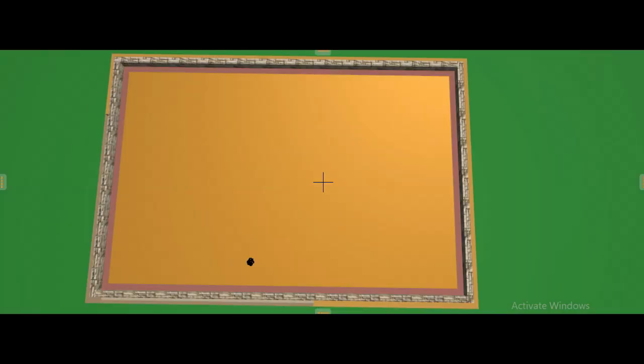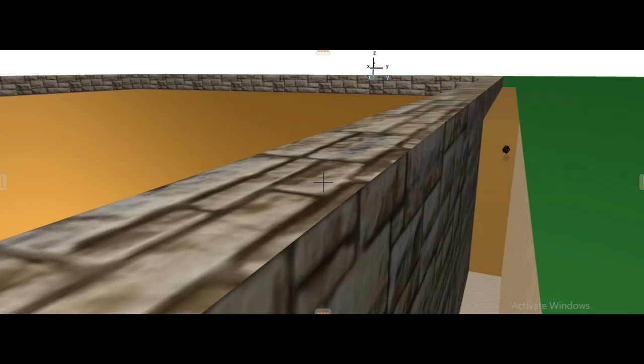And now if I'm interested to get the volume of this excavated material that is supposed to be used to do the backfilling, I'm going to get a mean gap all around, and multiply that mean gap by the width, that is from this end up to this end, that is 0.2 meters, by this depth now, which according to our dimensioning was 1.00.